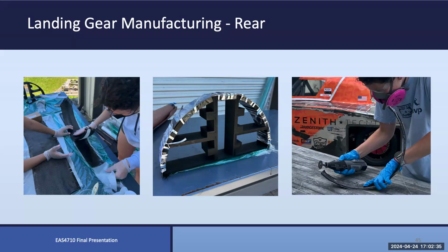Carbon fiber gives you a lot of opportunity to maintain strength, but also tune stiffness and control things like impulse loads. So that's maybe something to consider going forward as a future iteration on this if you take it any further.